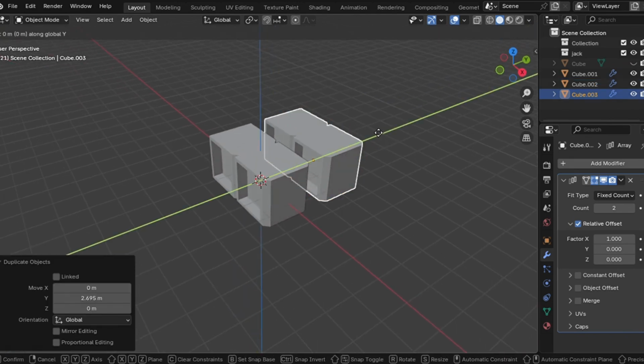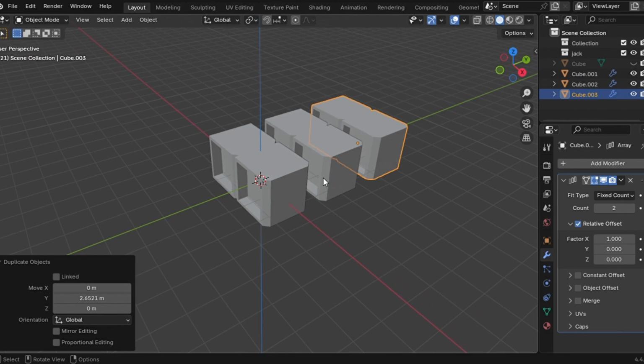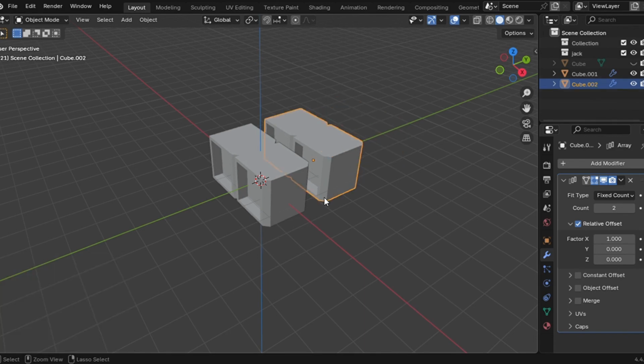If you want to do it 5 times, it might not seem like a big task, but if you're doing it 1,000 times or 100 times, it can be painful, right? And suddenly, if you change your mind and you don't want to duplicate on the z-axis or the y-axis, it's really painful and frustrating. That is why we're using a modifier, because a modifier is non-destructive.